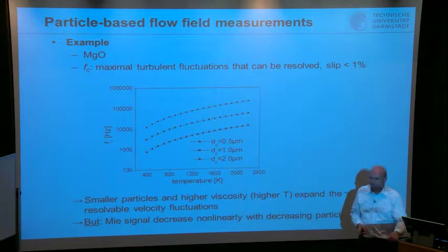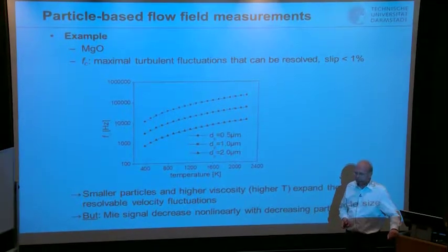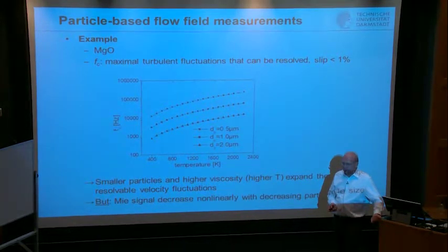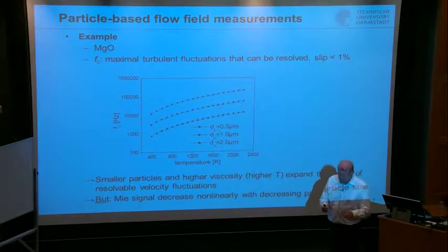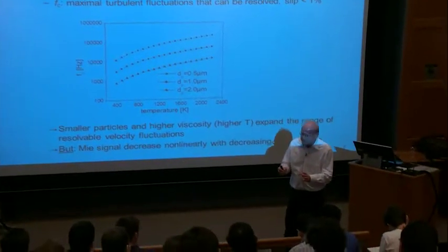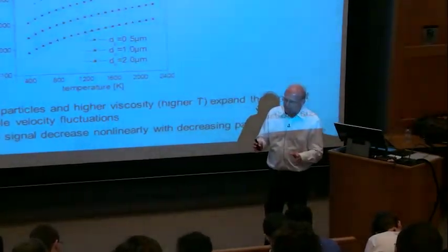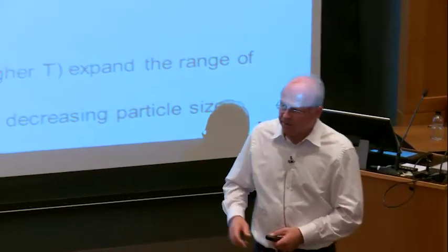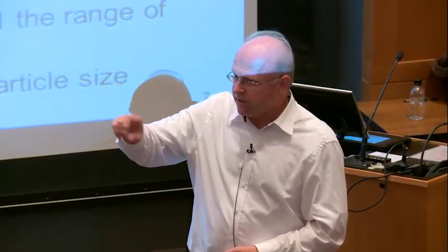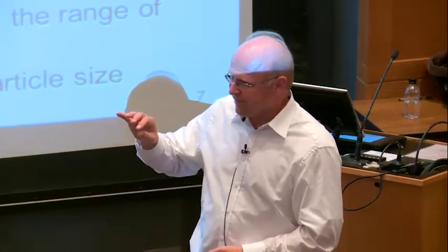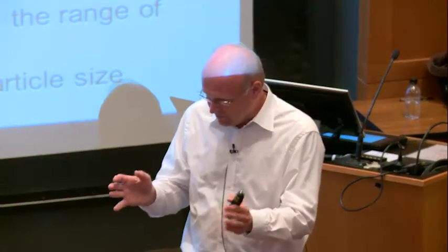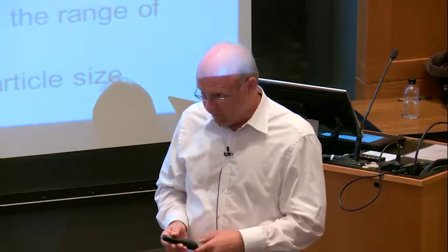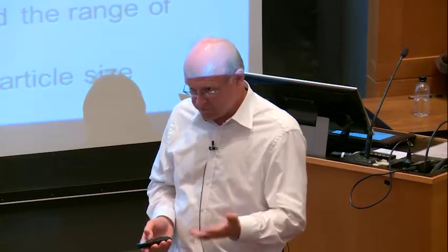Okay, your question. I was just curious, for the seeding materials, what properties other than a low density and high melting point would you want your seeding materials to have? You want them not to stick to each other, because typically that is a problem, unless you have dried air. In my lab, I have the infrastructure to dry the air to a dew point of 2C, and that helps. But if the seeding material is in your tank and you cannot prevent any humidity, that's a very, very important quantity. Yeah, to say another one.